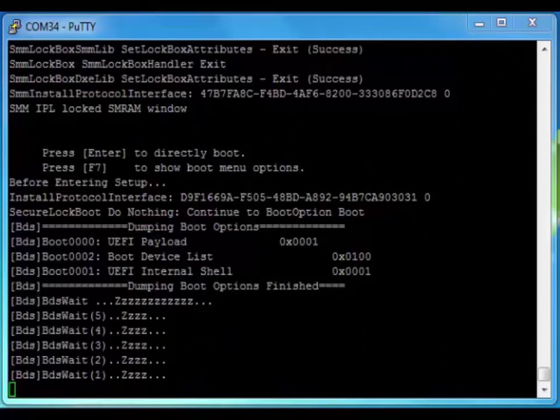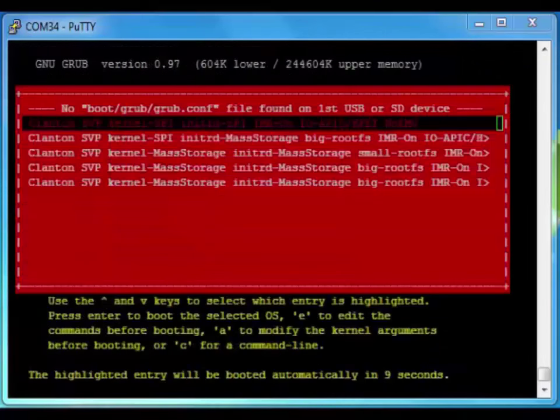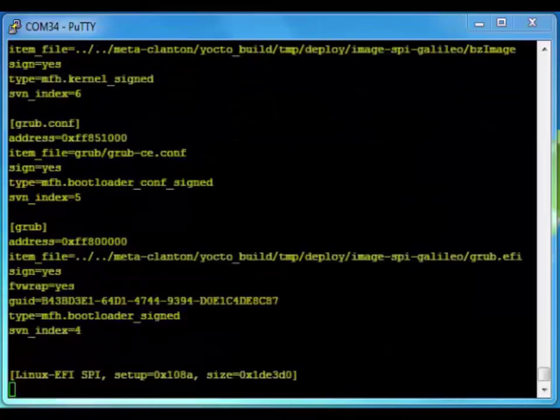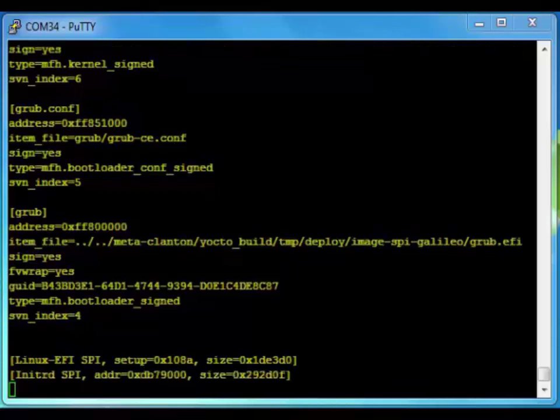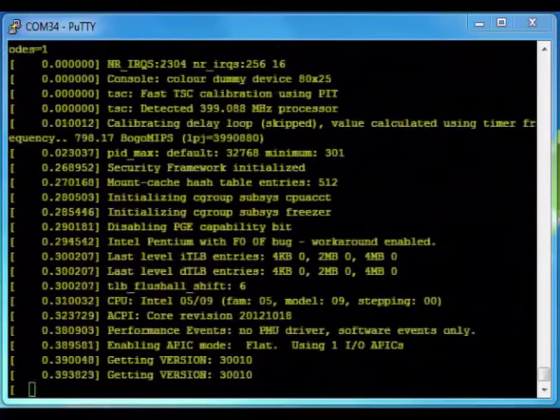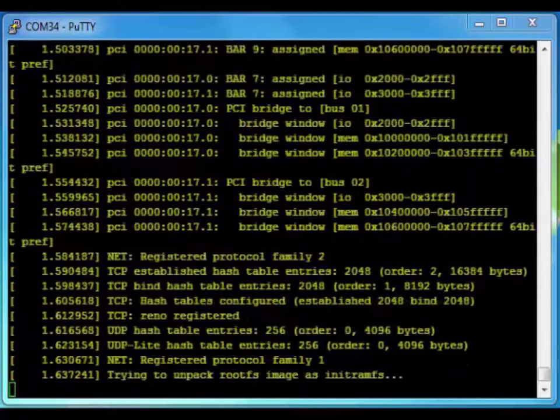Note that for a Galileo board, the following two methods will work only if the Linux kernel images have uClibc support. This is because images providing uClibc support are required to download Arduino sketches to Galileo. The other flavor of glibc, which is the eglibc in Galileo Linux images, does not activate the USB client driver on Galileo, and thus we cannot download sketches on the board using Arduino.